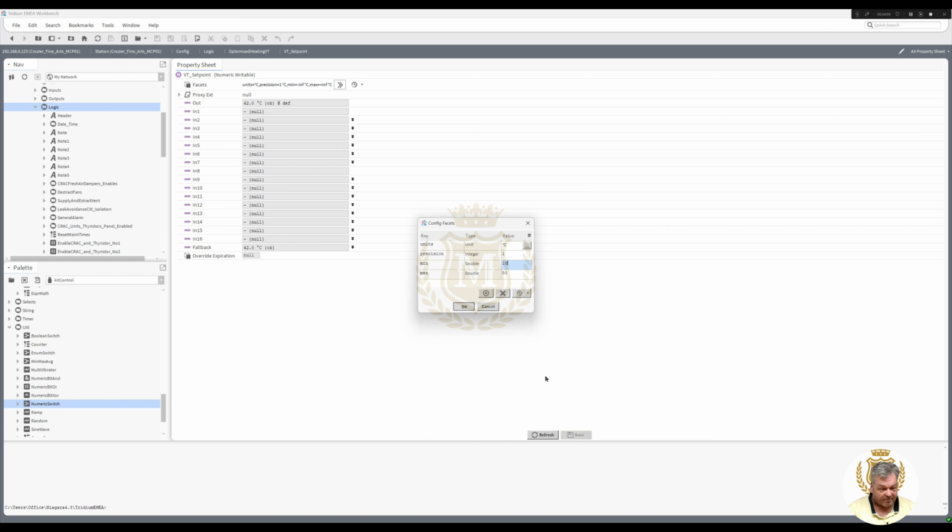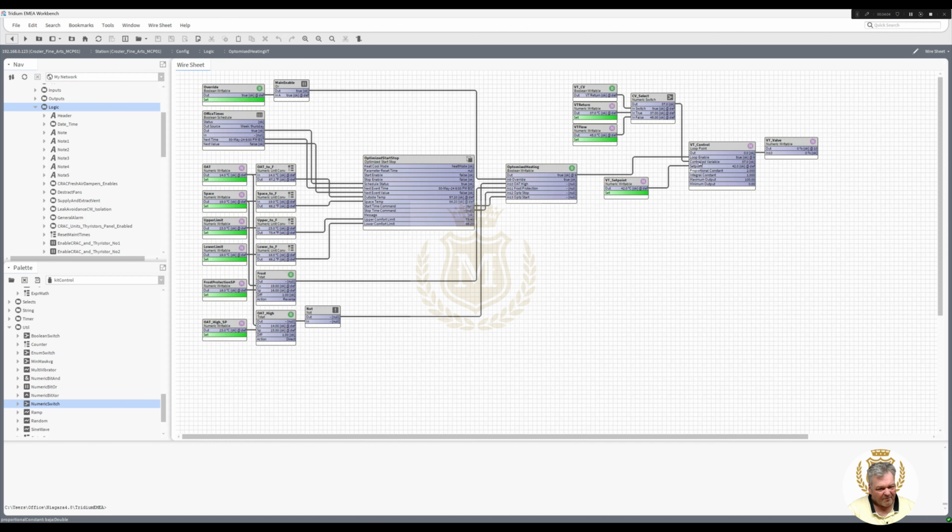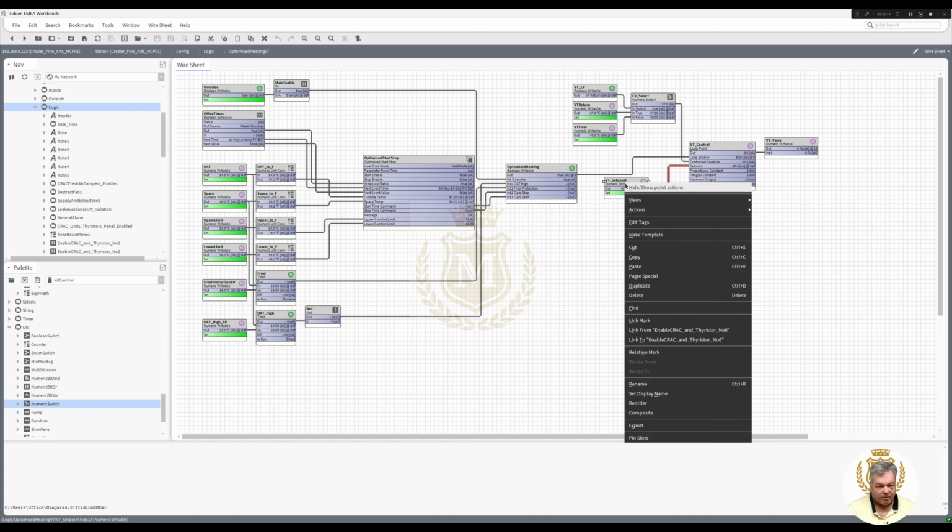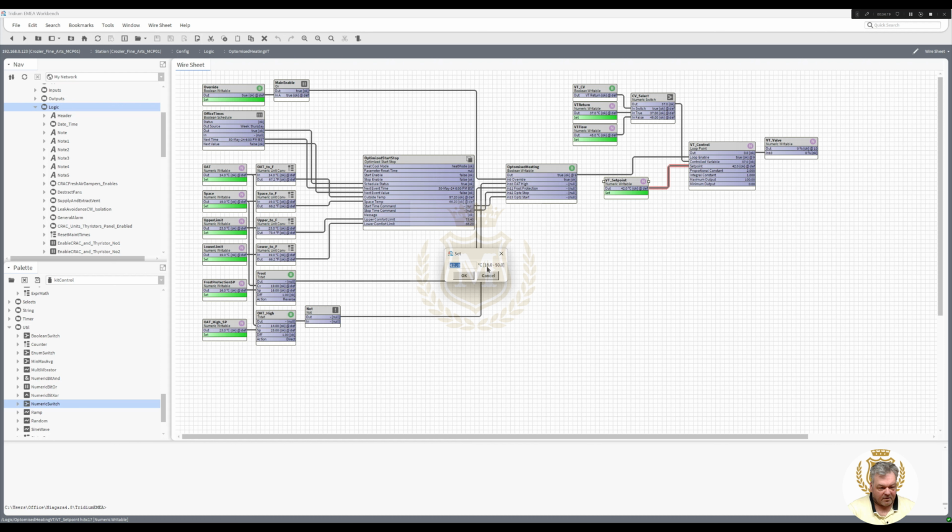So we give them some limits to work with, depending on what system the VT, the variable temperature, is actually running to. But so we've given limits there, so when they actually come to do the set point and they come to set it, they've got a limit between 18 and 50. They can't go above 50 and they can't go below 18. 18 is really low.